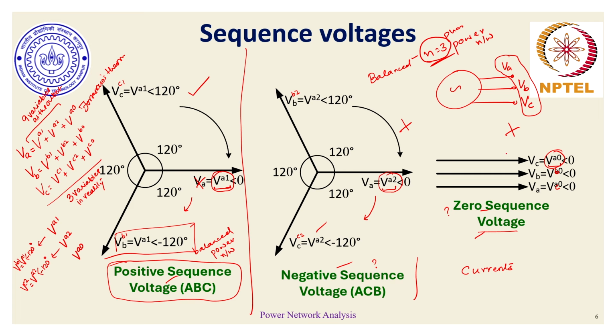And as per the zero sequence diagram, where the phase voltages are again equal and the phase angle is 0 degrees, VB0 is the same as VA0, which is the same as VC0. So in a way, if I know these three sequence components, I can identify the remaining six components.